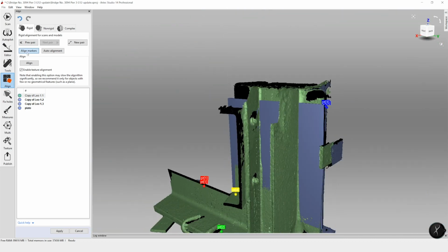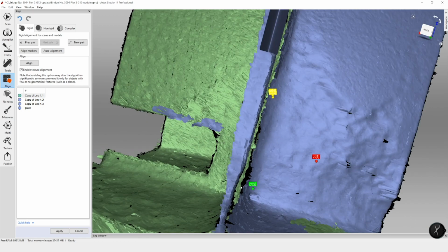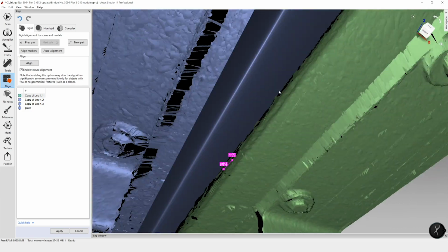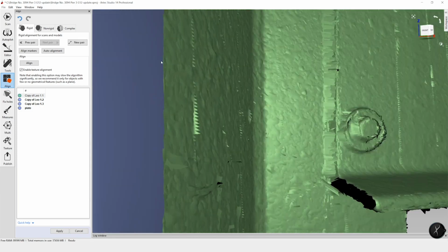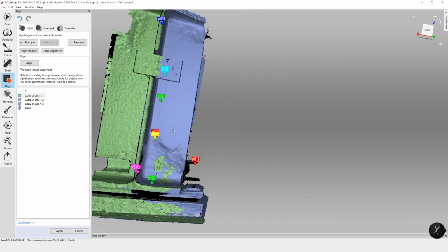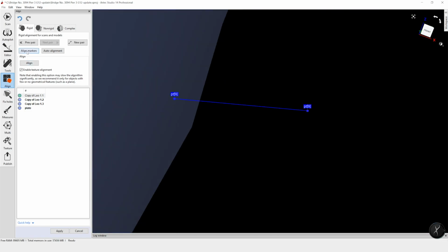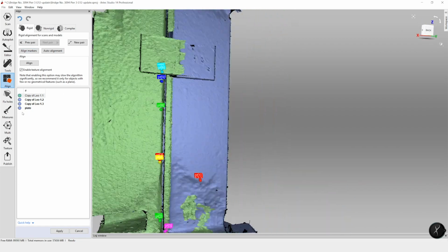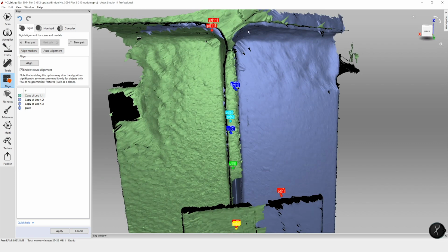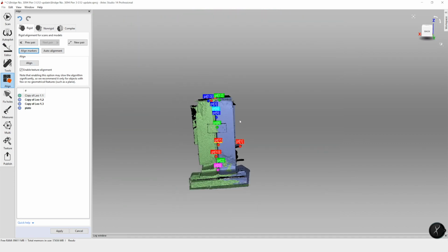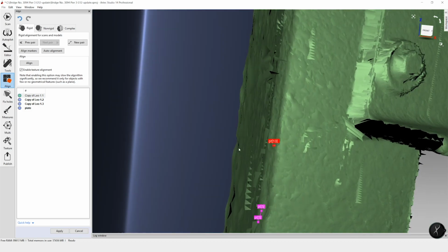We've already run global registration on the individual frames, and that's normally our other opportunity to do an alignment of sorts by registering all those scans together. Since we've already done this, how the alignment looks in these frames is going to be our final alignment before fusion. So make sure you take your time and really do your due diligence when you're selecting these points, checking the target bar and the other areas of overlap, front of the web, making sure that our alignment looks consistent along the length, along the width, underneath, and on our target bars, so we're not having any problems before fusion again, because otherwise we're going to have to come back and do this process again.